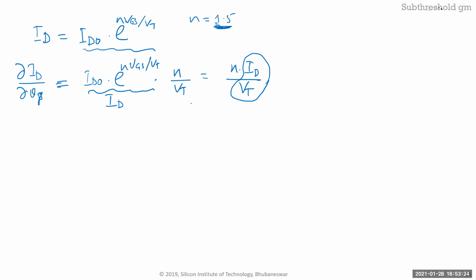Like I was saying when we did the VT in the last lecture, when the channel is formed, it starts conducting. No, it's actually conducting before that, but it's conducting like a BJT. It's through diffusion. There is no drift because there is no channel charge. But that's fine. For low power ones, I don't want a ton of current. I want the variation of current to be large with a small variation of VGS.